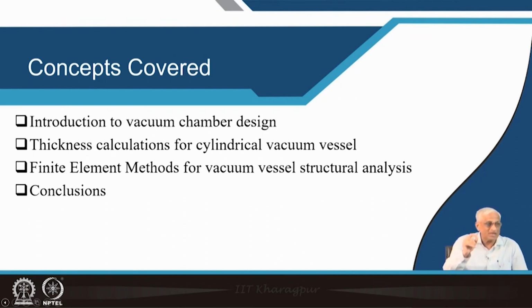So if the material is not properly polished, the molecules, particularly in molecular flow situations and ultra high vacuum conditions, are exposed to a very large surface area because they can go into the internal micro cavities because of roughness. So that is also very important in chamber manufacturing. So thickness calculation, some thermal issues, and finally the surface finish: all these things should be decided before you take up the fabrication of a vacuum chamber.